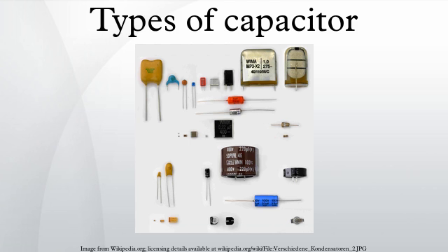They also have significantly lower parasitic inductance, making them suitable for higher frequency applications, due to their construction with end-surface contacting of the electrodes. To increase the range of frequencies, often an electrolytic capacitor is connected in parallel with a ceramic or film capacitor. Many new developments are targeted at reducing parasitic inductance. This increases the resonance frequency of the capacitor and, for example, can follow the constantly increasing switching speed of digital circuits. Miniaturization, especially in the SMD multi-layer ceramic chip capacitors, increases the resonance frequency.